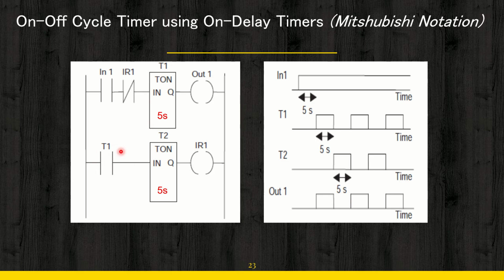It is a normally open contact, because ultimately your timer on is going to have a relay at its output, virtually there will be a relay at its output, so the relay will have two contacts, one T1 and the other T1 not, that means the reverse contact. So here you can see this is the NO contact, we have not connected the NC contact here. Now try to find what is happening.